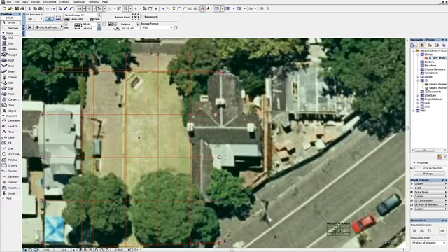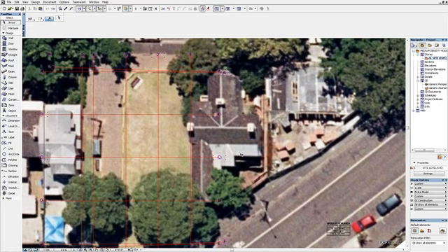Okay, let's have a look at this roof shape. So the roof is a multi-plane roof, and we've got a ridge line here and a ridge line here. It looks like these ridge lines are meeting at the same RL level, or the same relative level above project zero. This one we can't be sure, but it might seem that this ridge line is lower because it does not reach all the way to this ridge line. It's only reaching to here, which would indicate that it's further down and is hitting this roof plane at this point.